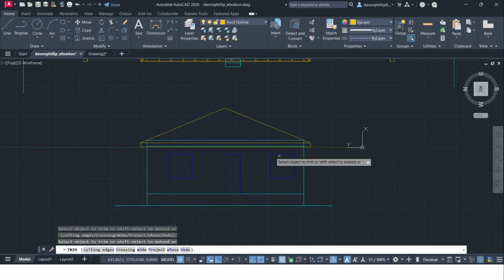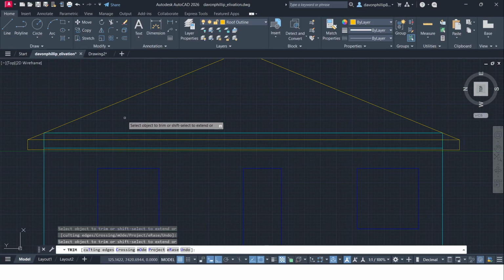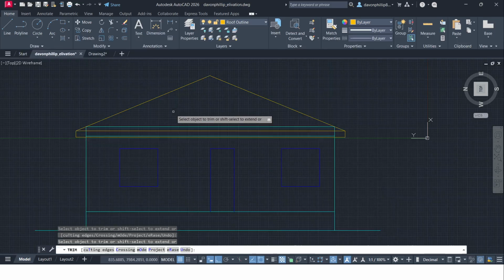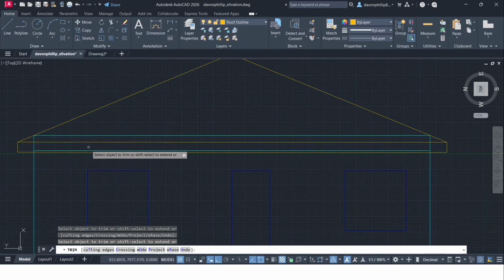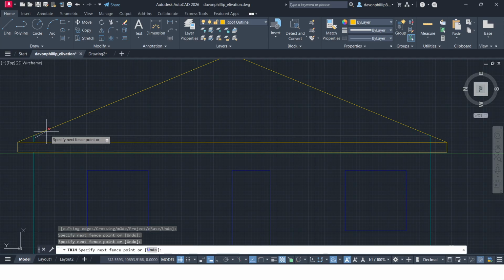But when we look at it, the building part is still kind of weird. Now, when you're drawing the building, do not be lazy and skip this top part because you're going to erase it anyway. You must do it because when they are taking the measurements to grade your elevation, if you don't do this part here, the 300 on the top of the building, your roof is going to be off and they're going to take marks off. So you definitely should try it.